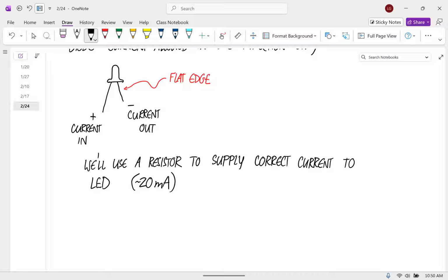By the way, if you have one that has 4 color bands, and the fourth one is gold or silver, those just tell you how precise the resistance is. So these aren't exactly 330. They're somewhere in the ballpark of 330. That last band, a metallic color, just tells you how close you can expect it to be to 330, depending on how precise your application is. Obviously, it costs a little more to get more precise resistors.